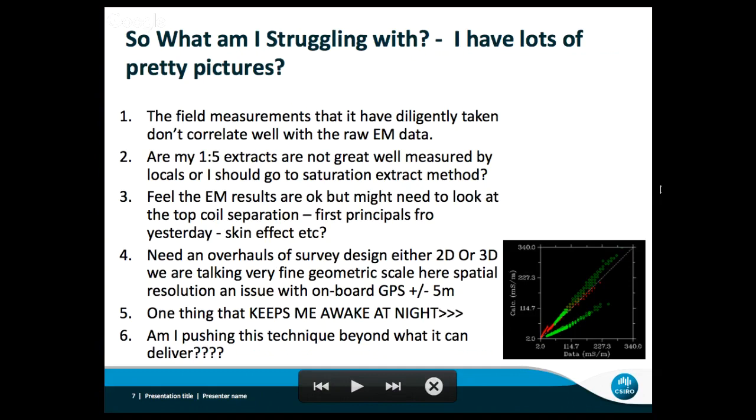So we just rank the conductances and break it in. We think we've got time to dig 10 sample holes. We'll break it into 10 even conductivity bands, pick those points, and then go and sample those points for one of the coil separations. That's how we sample.